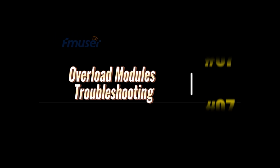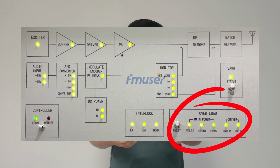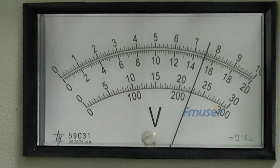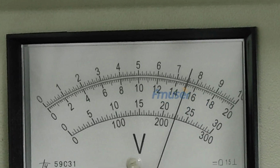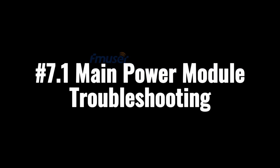Step number 7. Transmitter overload monitoring and shutdown. The overload module continuously monitors the RF output of the amplifiers, alerting the operator through prompts or indicator lights if any overload or issues are detected. When any of these values exceed the predetermined threshold, protective measures are activated. The main power module troubleshooting.